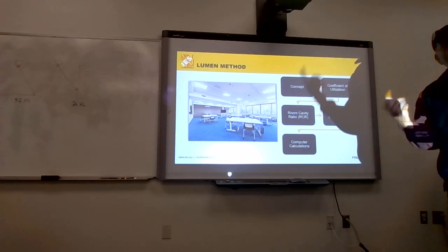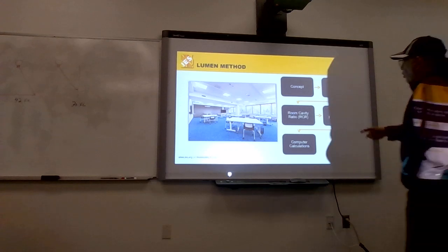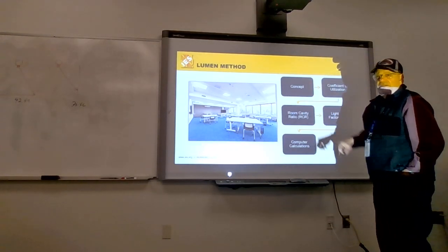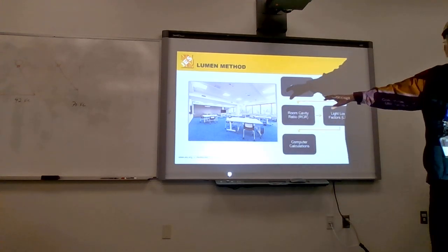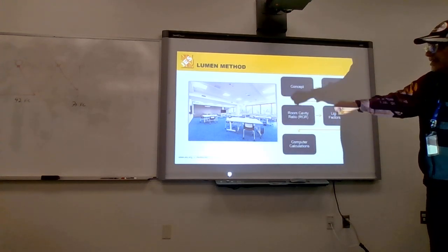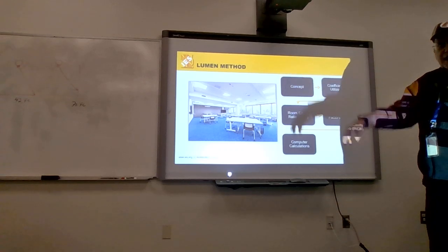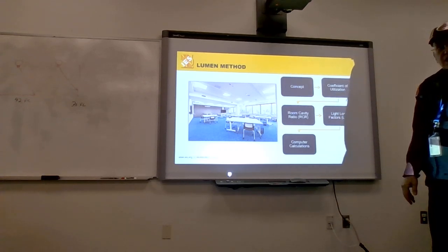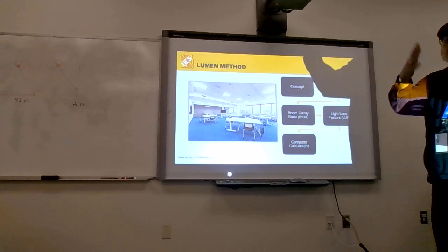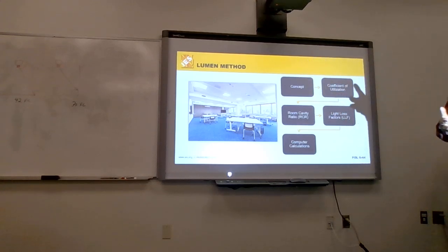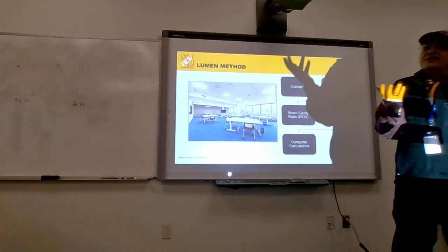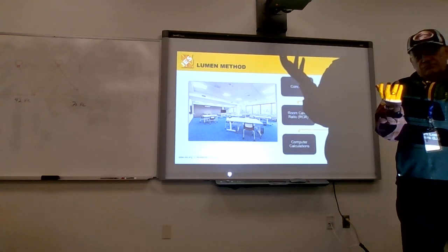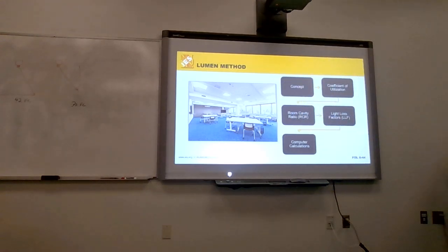We can generate the number of luminaires needed for our concept foot candles. And the concept sometimes is by law that says in the state of Connecticut you must provide 50 foot candles in a classroom. That may be something that's generally accepted. The authority having jurisdiction, if you remember that, they may say 50 foot candles in the classroom, deliver it. Well, how many luminaires do I need to deliver 50 foot candles? Right? That's one question.